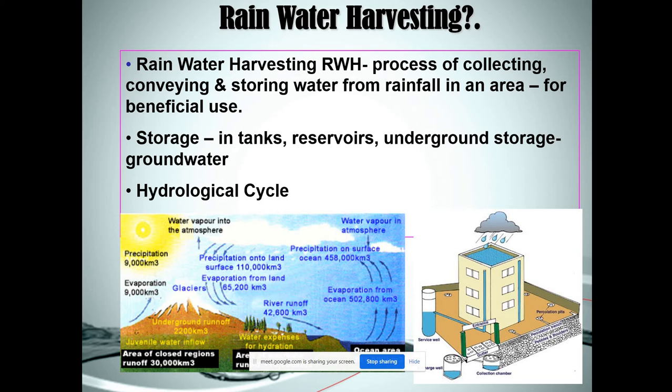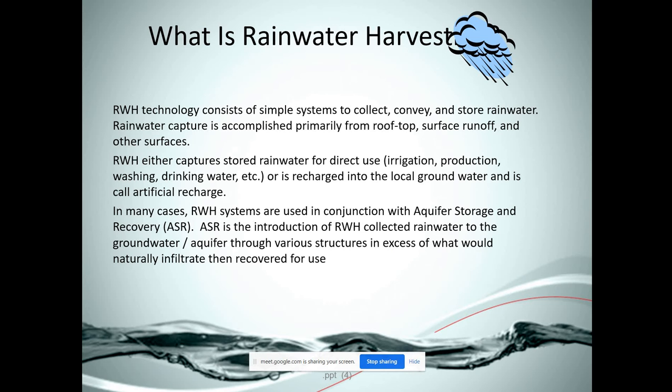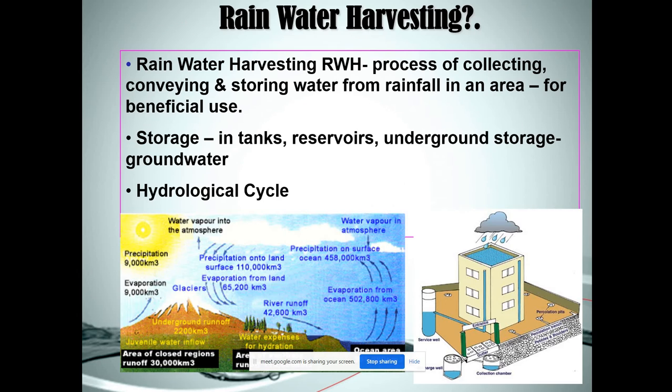Rainwater as source water design consideration. First one is roof, second is screen, third one is discharge of water, fourth is pre-filter, fifth is storage tank, sixth is flow meter, and seventh is storm water discharge. Groundwater recharge. Under natural conditions, it may take days to centuries to recharge groundwater by rainwater. As we need to replace the pumped water, artificial recharge of groundwater is required at some locations.